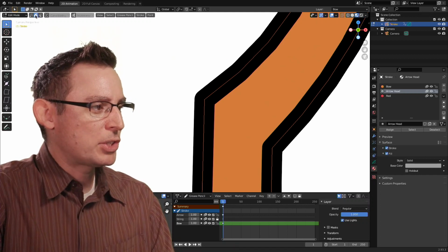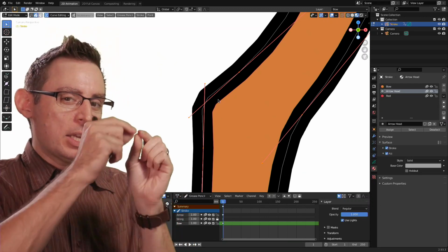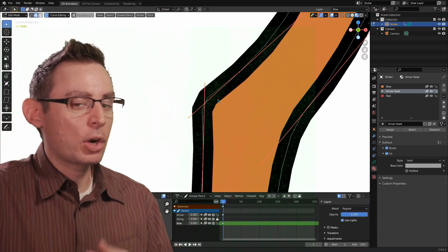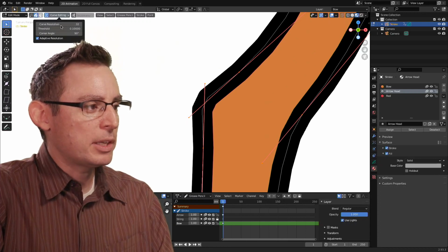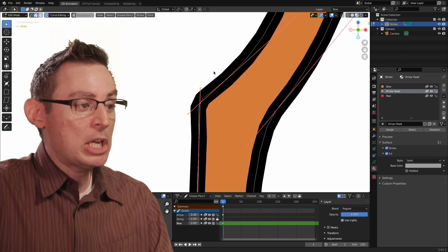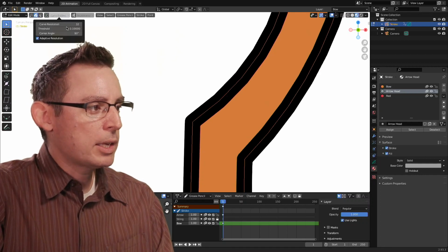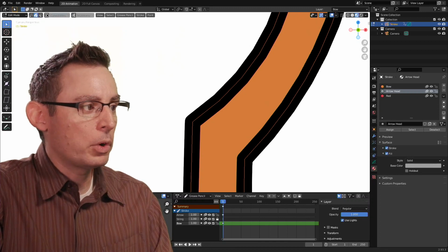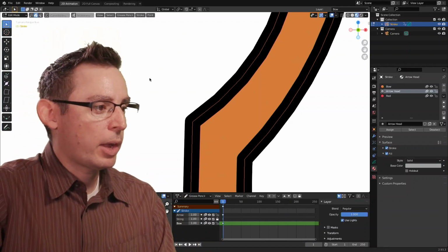I'm in my stroke selection set. If I enable my curve editing, it's going to reproject the curve. So it's taking all the dots that create that stroke and it's reprojecting that. It's recreating the curve based on some new parameters. And specifically, it's reprojecting it with this information in here. We can increase the quality. We can increase the simplification of the curve. So experiment around with it. Let me hit undo real fast. If you'd like, definitely make some adjustments to the curve resolution, threshold, and angle before you reproject the curve. That way those settings are applied to the curve when you reproject it. Okay, I'm just going to roll with the defaults.